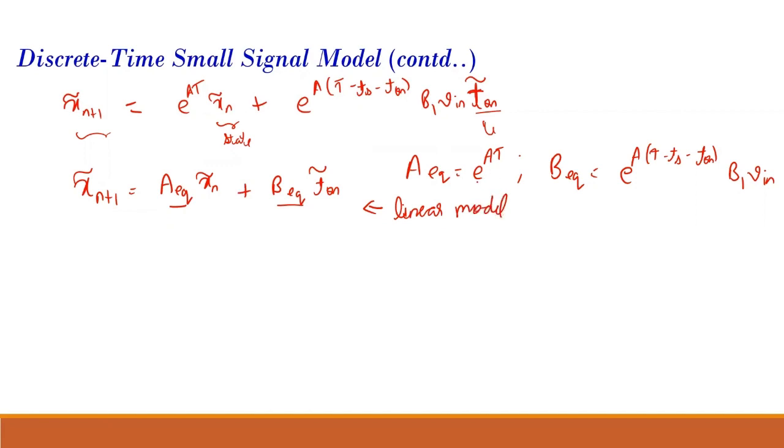So now if you see, this is a constant value. Okay, this also is a constant value. So the discrete time large signal model, I have linearized it using this Jacobian and this Taylor series, etc. And I have brought it into this form. Once I brought it into this form, then I can find the discrete time small signal transfer functions of it. So any doubts still here?